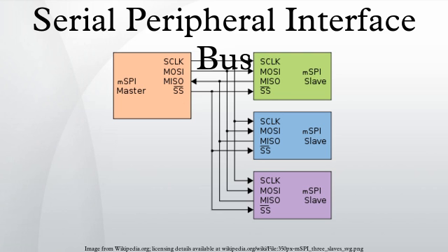This significantly reduces overhead compared to the LPC bus, whose throughput is nearly totally dominated by overhead. The standard memory cycle allows a length of anywhere from 1 byte to 4 KB in order to allow its overhead to be amortized over a large transaction. ESPI slaves are allowed to initiate bus master versions of all of the memory cycles. Bus master I/O cycles, which were introduced by the LPC bus specification, and ISA-style DMA, including the 32-bit variant introduced by the LPC bus specification, are not present in ESPI. Therefore, bus master memory cycles are the only allowed DMA in this standard.